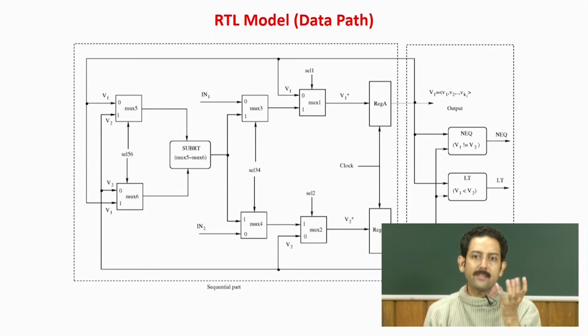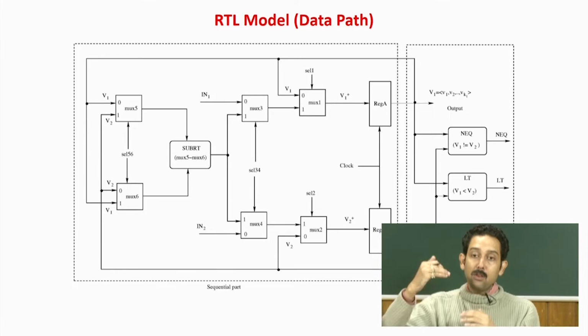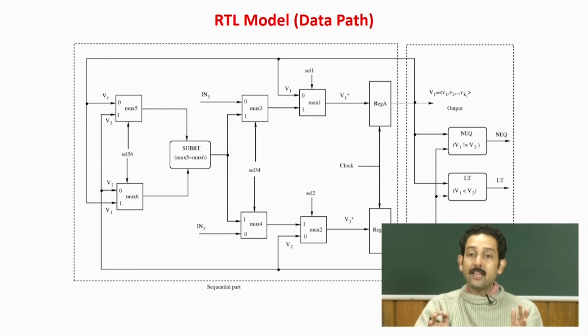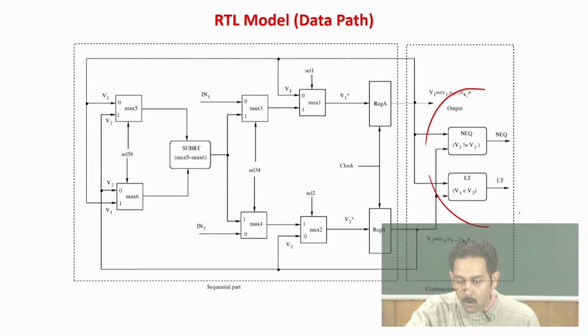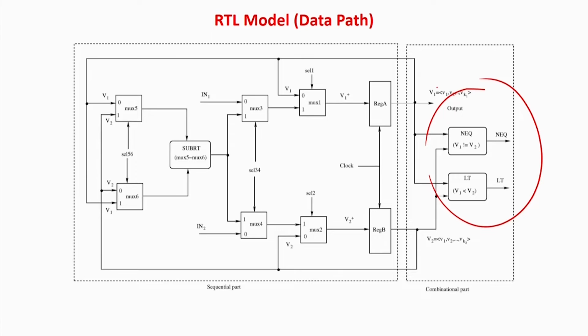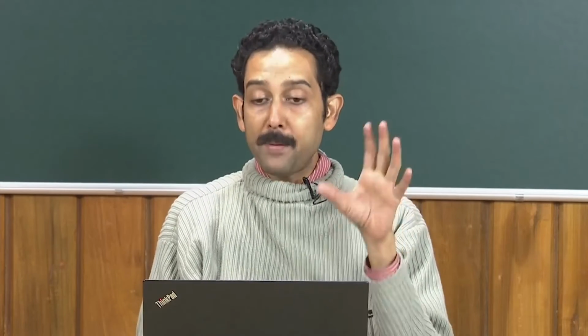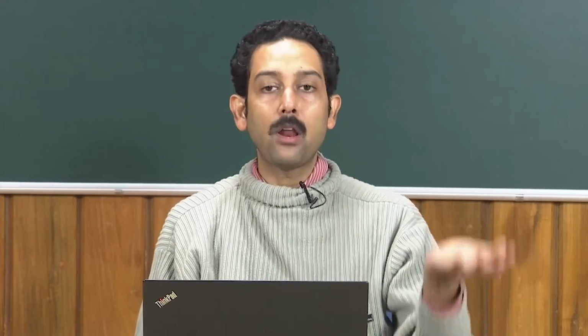The controller is generally a small finite state machine, which is smaller in size compared to an RTL design data path. So if the bit width of the numbers increases, like in1 going from 32 bit to 128 bit, the size of the data path will be enormously large in terms of gates. But the controller will always be the same, because the controller takes the outputs of these combinational blocks, like V1 is V2, V1 not equal to V2, and gives the appropriate signals to control the multiplexers. So even in very large or very complex circuits, we are more concerned with the optimization for testing of the data path. The controller more or less remains similar whether you are taking a single bit number or a 128 bit number.